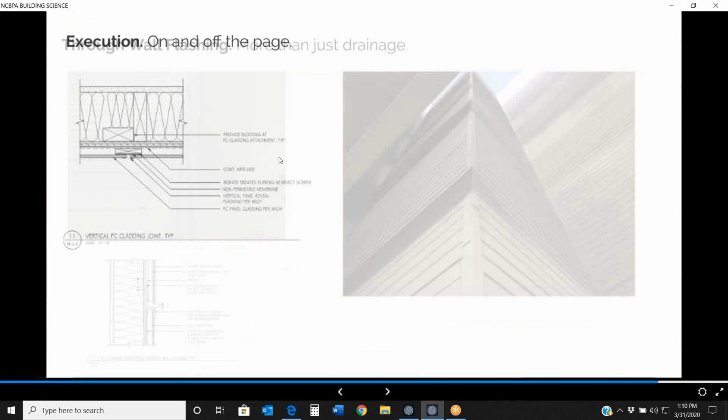one effect that came out of this is where the concrete parking garage tied in to the frame building, and just by coincidence, where this fiber cement trim had blown out, it had failed the sealant joint between the expansion joint and the building. So this is definitely a place where some improvement needed to take place. And one of the things we could have saved was the through-wall flashing. So I like to bring it in.